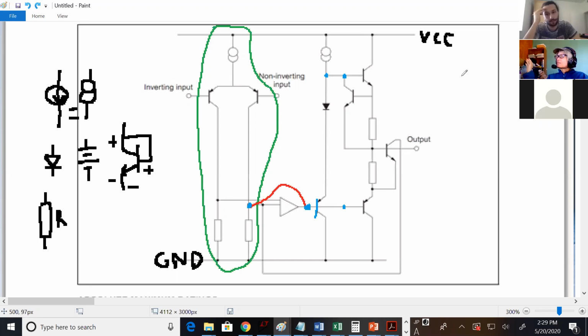If you have two circuits that work great, and then you connect them together and they stop working, what's probably the problem? Oh, loading? Loading. Exactly. So whoever designed this tried to connect the diff pair up to the output stage and it failed. He said, well, shoot, we have to do something here.